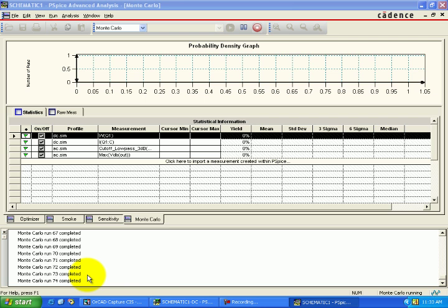Now as we have specifications for the cutoff, specification for the gain, specification for the maximum level of current that should flow from Q1, and maximum power dissipation, this analysis will tell us how many of these values are exceeding the limit and how many are inside the limit. If the values are inside the limit, that will be the particular point of the parameter changes in the component value. So this analysis says that, okay, for that particular value, if it's 10% tolerance, then from this to this is okay.